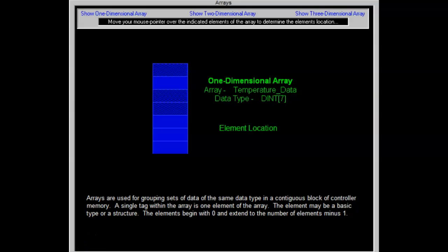In an array, there are element addresses and bit addresses. Each type may be numeric, fixed, or variable. The examples shown here have numeric addressing within the brackets. One or more numbers were placed inside the brackets. This makes the addresses fixed. To make an address a variable address, the following format is used: array, name, tag, or expression. An example of variable element addresses may be temperature data degrees Fahrenheit, ingredient data quantity -3. You will note that the example above includes a mathematical operator, the minus sign. Mathematical operators may be used in an array to specify an array element.